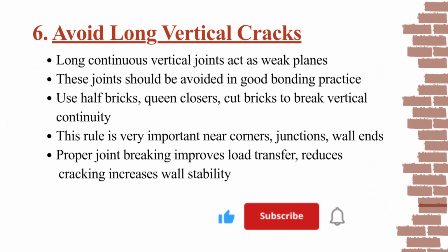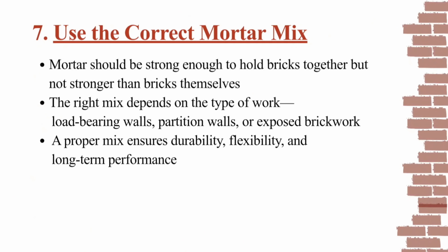So this is the important point. Now rule number 7. Use the correct mortar mix. Mortar should be strong enough to hold the bricks together but not stronger than the bricks themselves. If mortar is too strong, cracks may appear in the bricks instead of the joints.